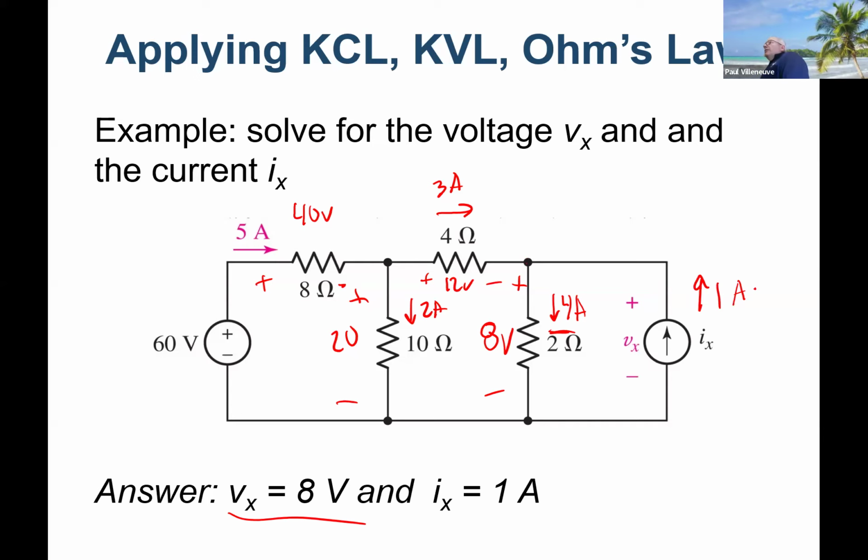So this was a combo. But what did you do? You all were thinking about it, and then the key was what Luke said, is finding that voltage drop. Once you find that, then you can find the next voltage, and then you can start to figure out currents and use the combination of KVL and KCL to walk through. You needed to use both, right? You couldn't calculate how much current was going through the 4 ohm resistor until you did a KVL loop and then a KCL for the node. And then you did that again, one more time, and you ended up with the final answer.